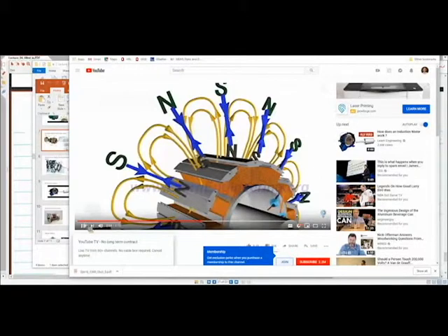And this rotational speed is directly tied to the power at the wall, right? So you have this big industrial machine that's plugged into three-phase power, directly tied to that. And what's nice about this type of system is that the frequency of the power at your wall is actually pretty stable, right? So you can directly use this power source to drive a system at a set speed.